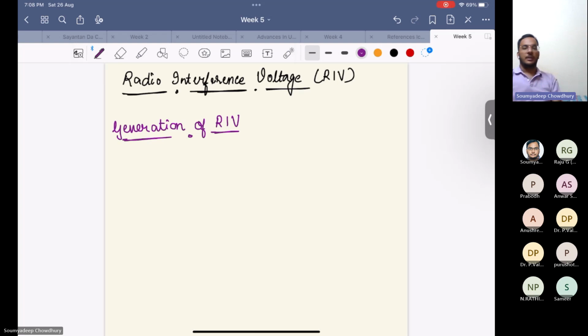Now if we go on increasing the voltage, electrons will be emitted from the surface of the electrode. Once the applied excitation crosses the work function of that metal electrode, electrons will be ejected from the surface of the cathode. Once these electrons are ejected, they are called the initiating electrons. These initiating electrons will collide with the neutral gaseous molecules.